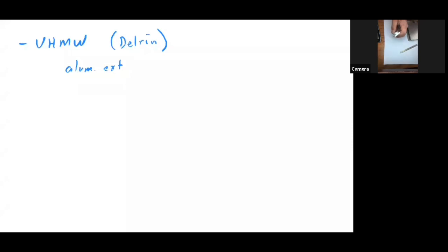If you have already done 440A, you're probably thinking about aluminum extrusion as a very flexible type of machine framing, because it's not welded together. You can bolt it together, and then when you find out your mistakes and your add-ons and feature creep that happens, you can go back and change it. So there's a real specific reason that we used aluminum extrusion to build machines.